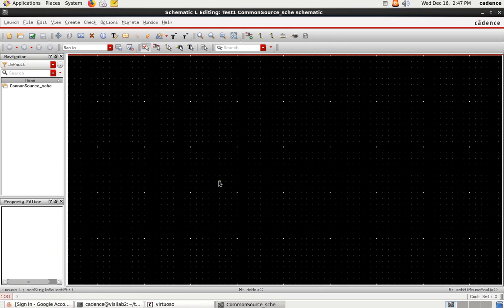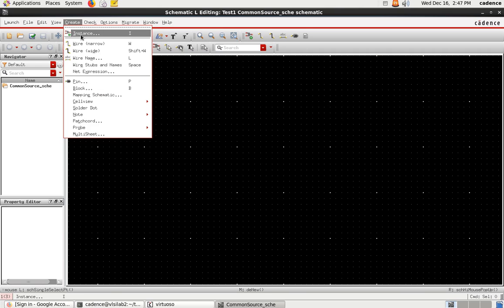In this video I'm not going to split the analog design steps. I'm going to explain the complete pre-layout simulation in one stretch, in one video. So now we have to add the instances for common source. Again, for common source, the PMOS is used as an active load or current load. First I have to go to create instance.